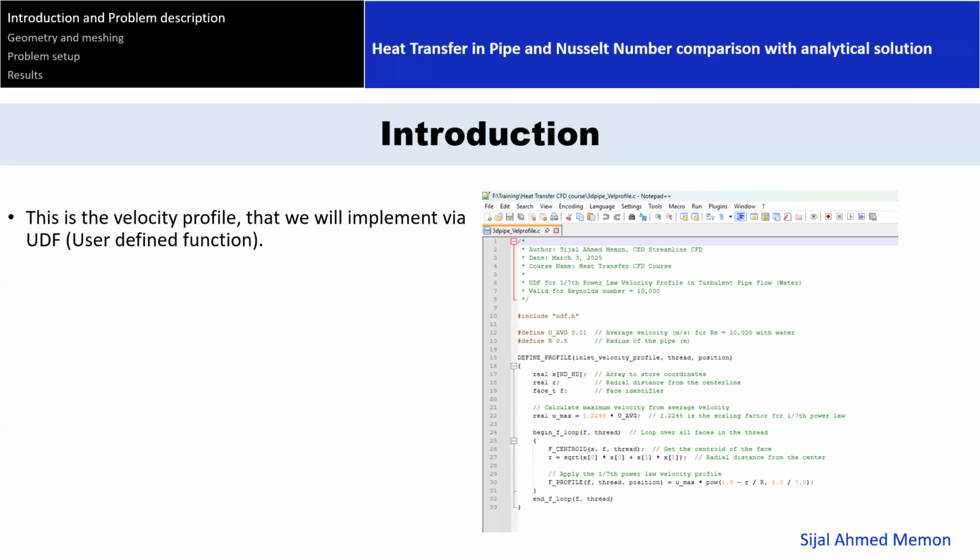Actually, this is only applied at the inlet, so we are talking about the inlet part only. So we consider the Y plus calculator, only the inlet velocities? No, no. I'm going to tell you how to use the Y plus calculator. The Y plus calculator depends not on the local velocities which are varying there. It only depends on the mean velocity.